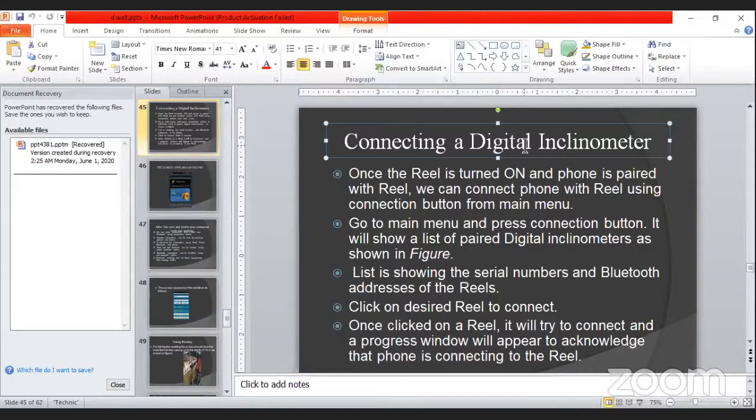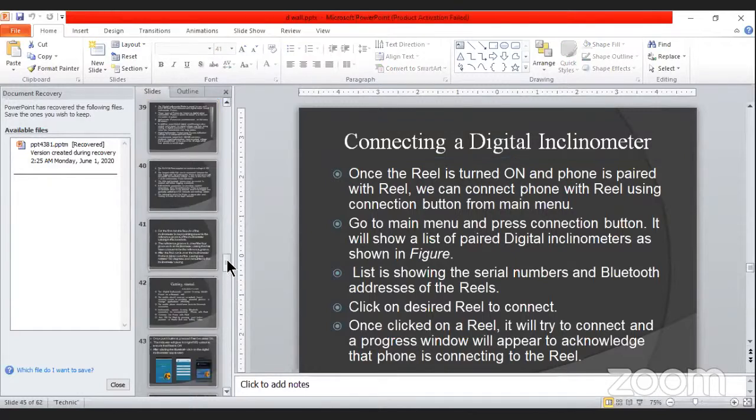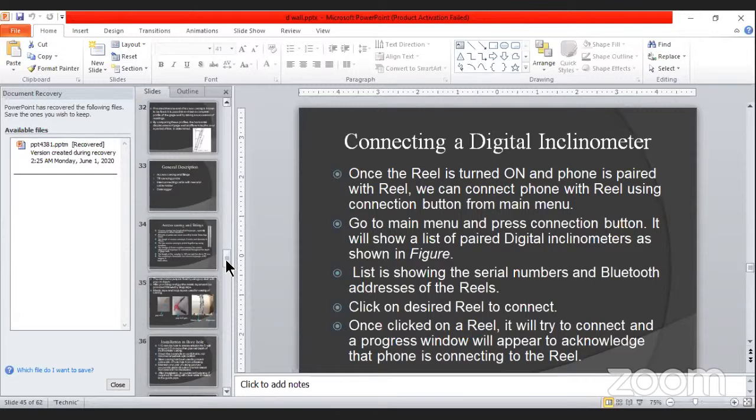But the maintenance is very easy. As I said, if we are putting water inside the PVC pipe and taking our readings daily, it is going to affect our machines. If you see the device, there is a ferrule with depth marks on it. We cannot say which depth we are taking the readings at otherwise, so that depth we have to maintain properly.